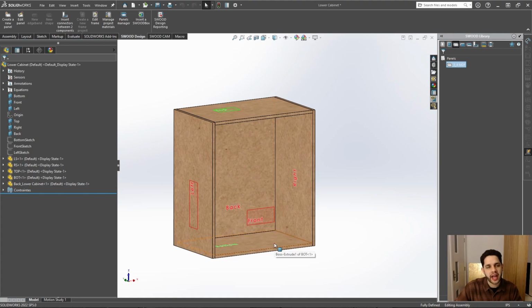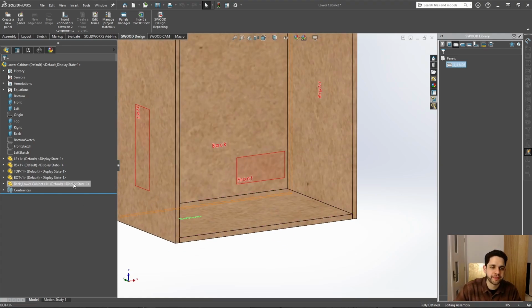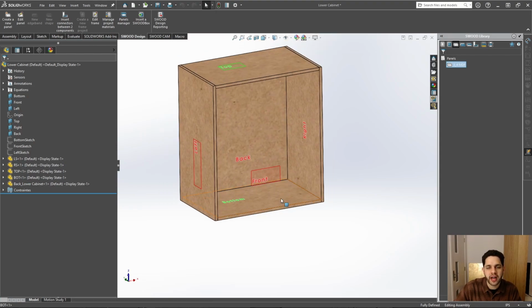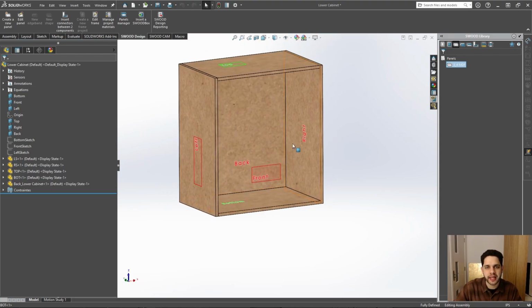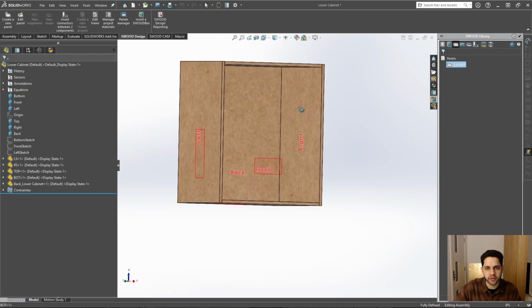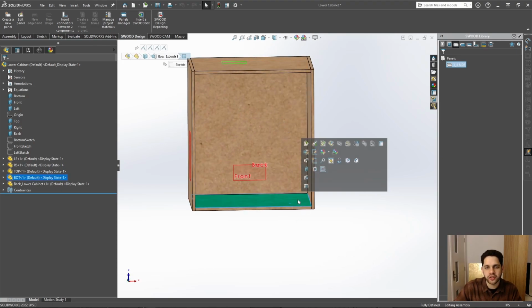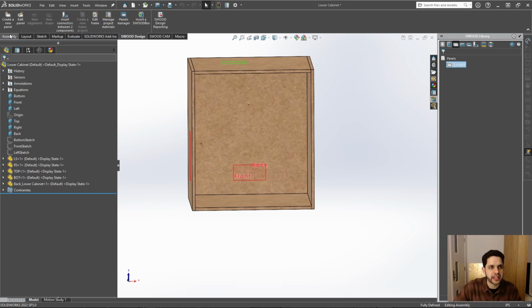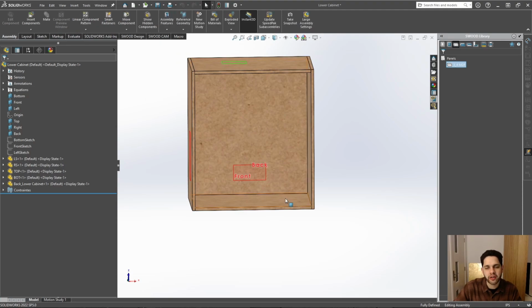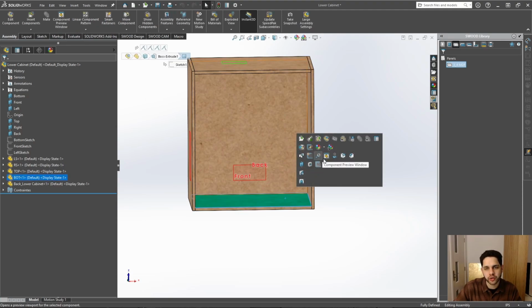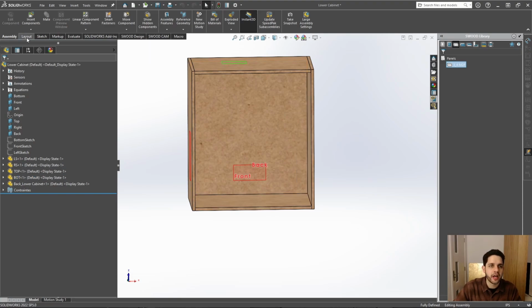And let's create a shelf. With the shelf, we want to be able to define where that shelf is in space inside of this frame. To do that, I'm going to create a plane. To get to your planes, I created a shortcut on my shortcut panel, and I have plane saved here.